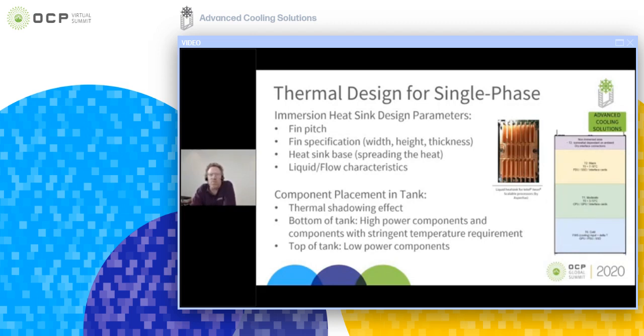You will find with proper analysis that a lot of the thicker fins will allow the energy to spread closer towards the fins' extremities, which allows more effective use of the surface area of a heatsink in liquid, whereas an air design heatsink doesn't really utilize the fins that are applied onto a heatsink.